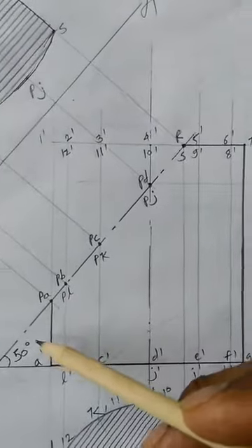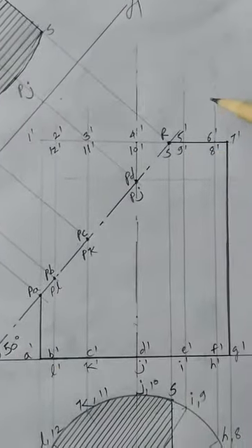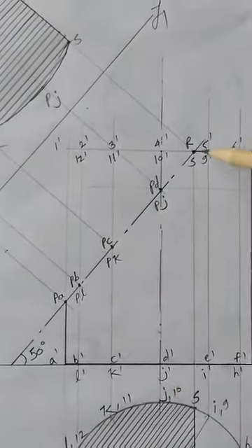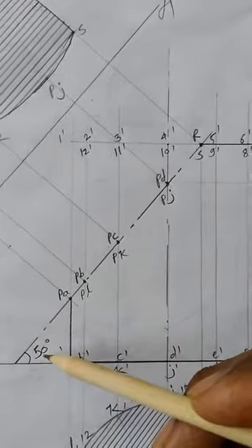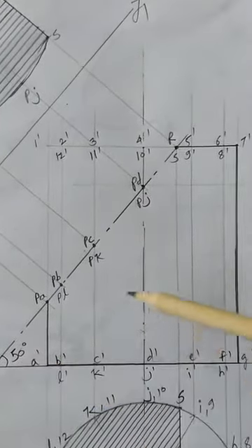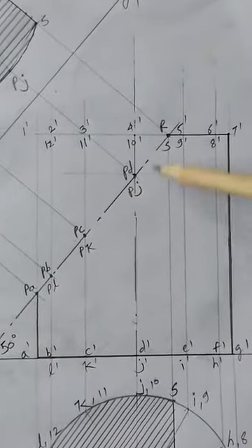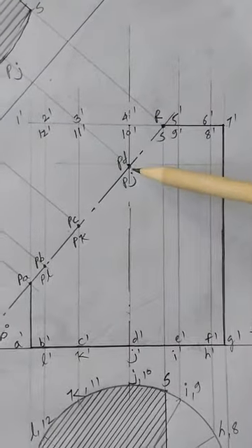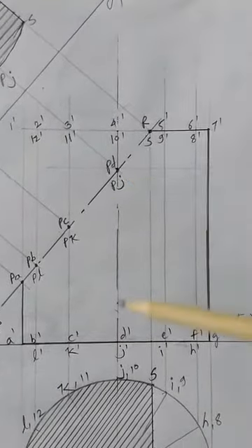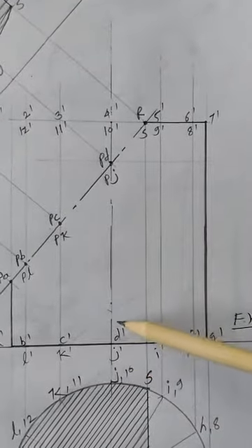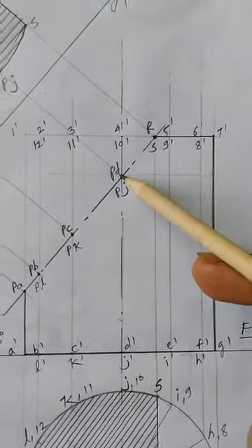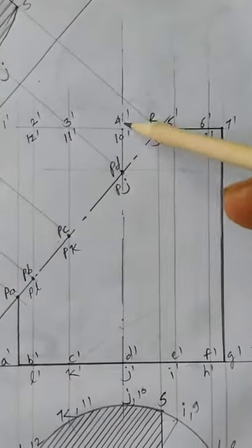After that, now cut this solid accordingly. It is mentioned that the cutting plane is inclined 50 degrees to HP, and it is passing through a point on the axis. This is the axis of the cylinder. The point through which the cutting plane is going to pass is at a distance of 65 mm above the base, or else 15 mm below the top face.